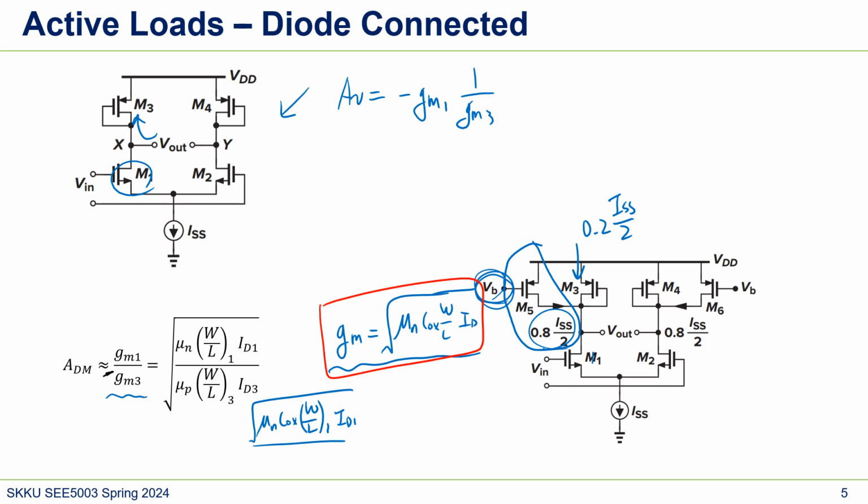And because the resistance looking here, let's say is just infinite, because the resistance here is small. What I'm saying is this way is 1 over gm4, but this way is RO4 or RO6. And 1 over gm4 is a lot smaller than RO6.